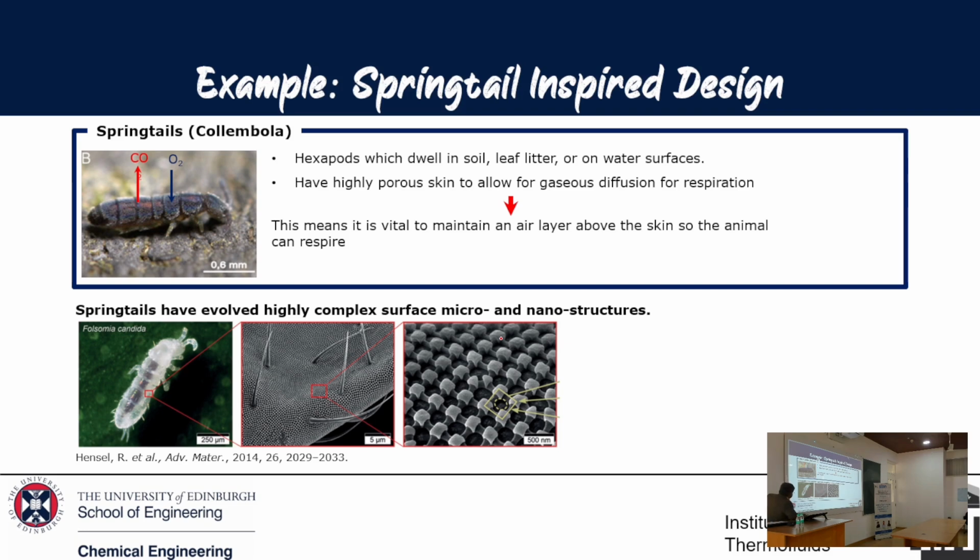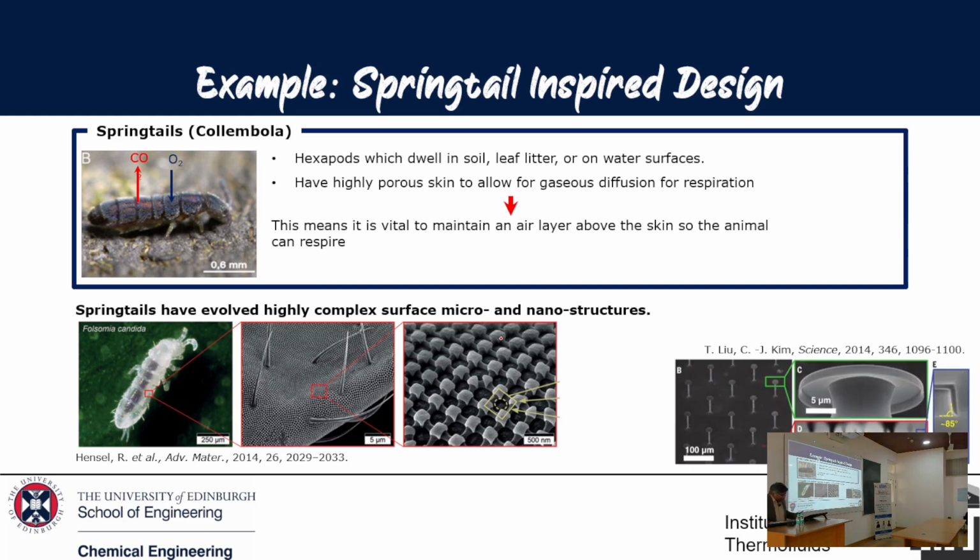So you've got these complex micro and nano structures. You can see that I'm not an experimentalist, I'm struggling to explain all these things. But what you can clearly see when you look at these structures is you've got these pillar-like structures, but then you've got these valleys, and these valleys are the ones where you need to take a lot of care, because if you want to make sure that it's hydrophobic, you need to encourage a Cassie-Baxter state. You should discourage a Wenzel state, so that you don't get trapping of liquid or anything, and that's a major challenge.